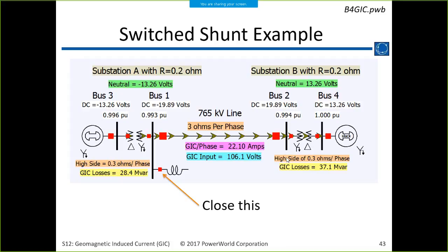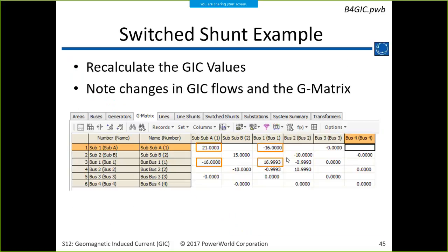I guess you could model those as, I mean, what we told customers to do before we put the ability in there to enter a resistance for inductors is just to model it as a transformer against a dummy bus. But I guess you could still do that. It's just oil and it doesn't have a magnetic core. So there's no saturation. There's no magnetic core, that's right. So just a big winding. Non-magnetic. All right, so that's appropriate then.